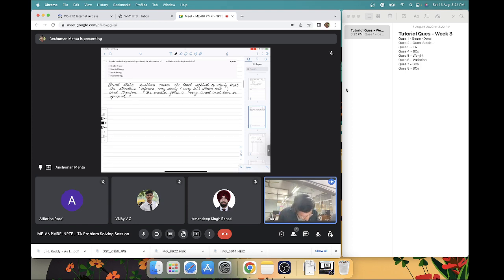So you would have seen this equation, right? For some force. It is a simple vibration equation without any damping. So in this, these forces are very small. So these are ignored because of very low strain rate, and hence whatever is left is kx is equal to f. So our problem of such nature is called a quasi-static problem.